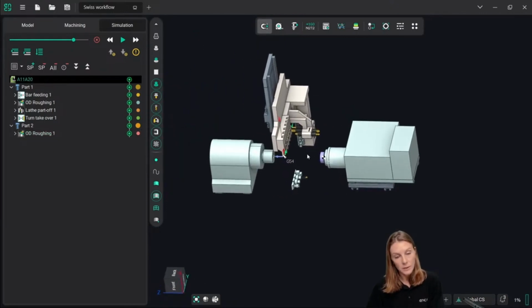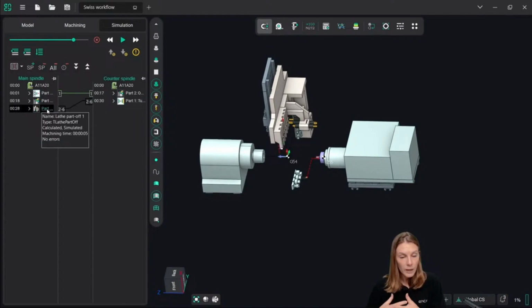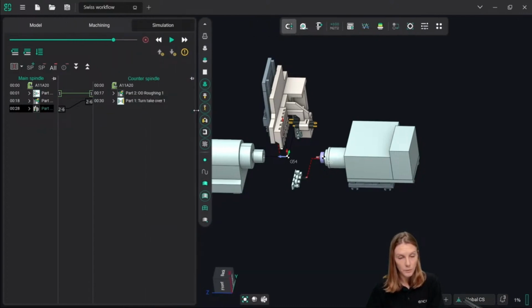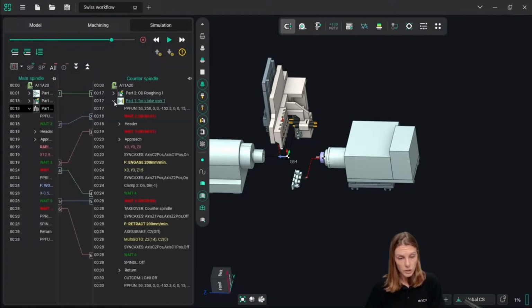the machining without real multi-channel mode. And this is the point where we can switch to the synchronized mode. The one benefit of Swiss lathe is really to make the operations simultaneously, and this workflow is managed in ENCY engine automatically. We do not apply any changes in the operations itself. We just change the mode and switch to multi-channel with SyncLines. And you have seen how the structure has changed.